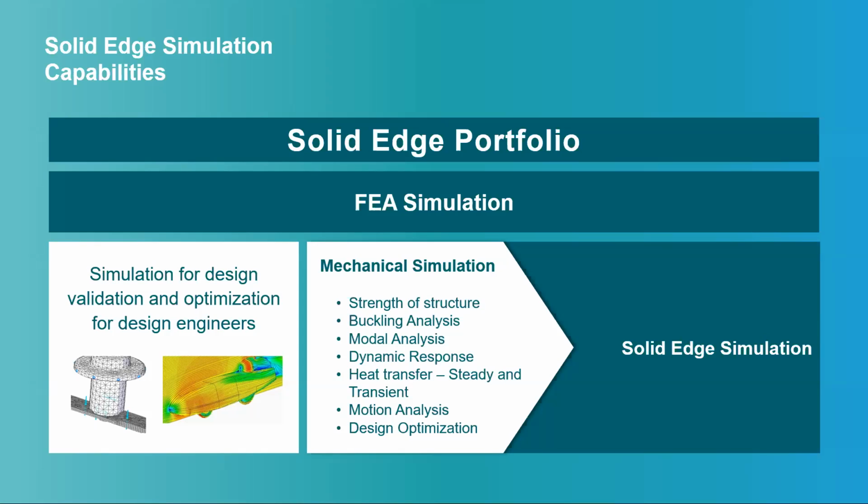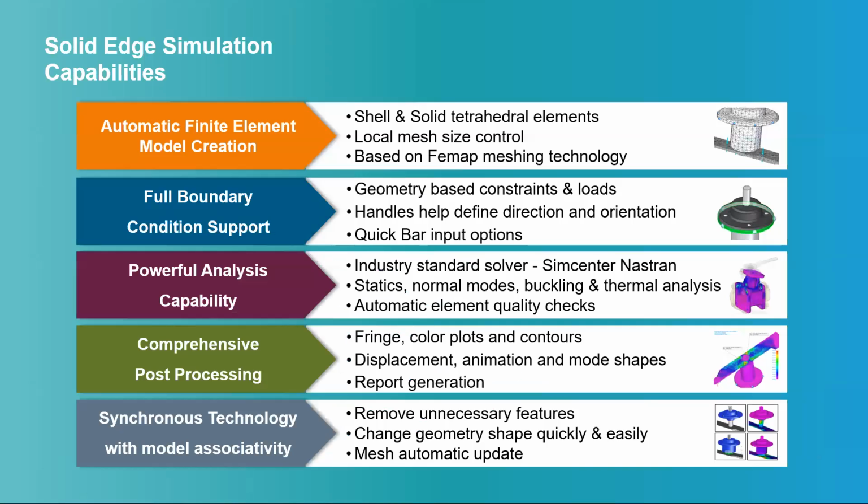So now the question is, what kind of analysis can we perform with Solid Edge Simulation? Well, in case you're looking for linear static, buckling, modal or vibration analysis, steady or transient heat transfer, or even motion analysis, we can perform all of this within Solid Edge Simulation. Then the question is, what about the capabilities? Well, with Solid Edge Simulation, we provide flexibility to the users. In case the users want the software to generate the required meshing, we have the option of automatic mesh. Or in case they want to have control over the mesh, then they can set it up themselves.